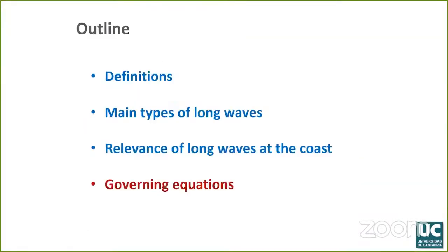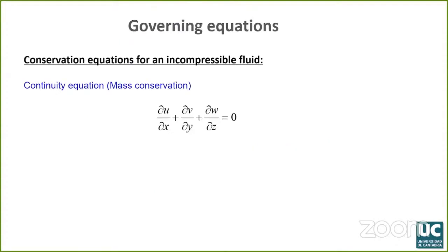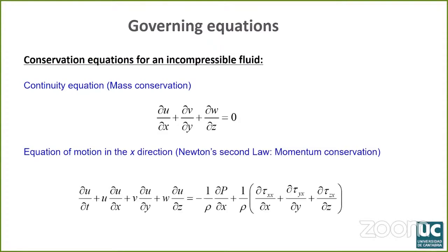Next, I will show you the equations that we have to apply to calculate sea level and currents due to long waves. We start with the conservation equations for an incompressible fluid, the continuity equation, and the three equations of conservation of momentum. Here is one of them, the equation in the x direction.